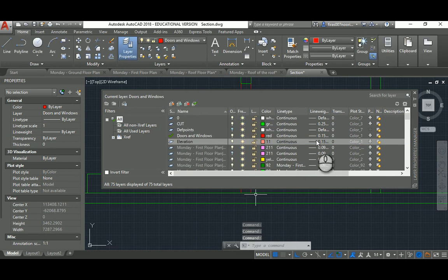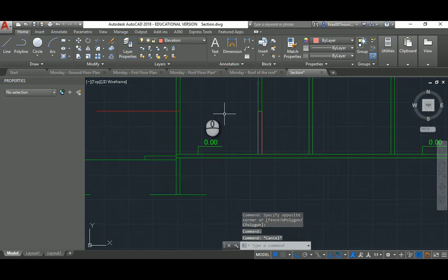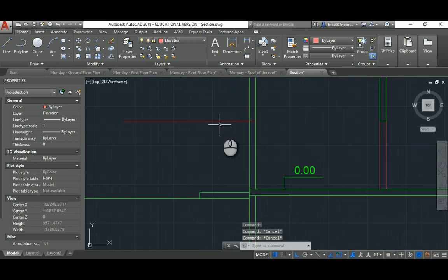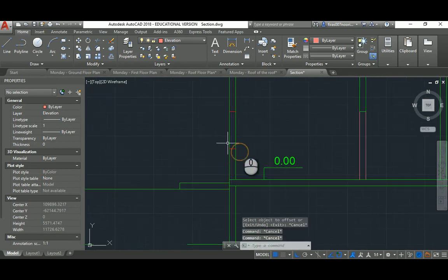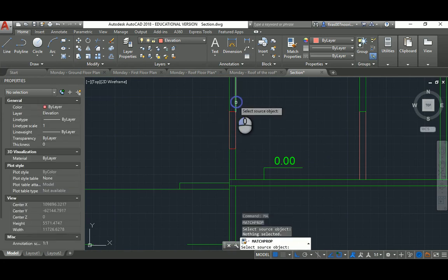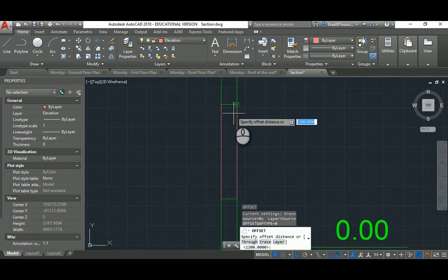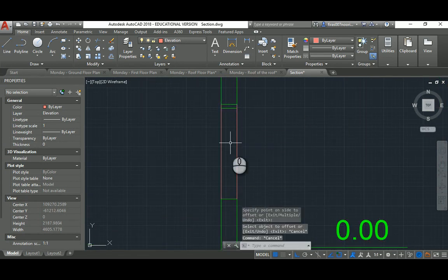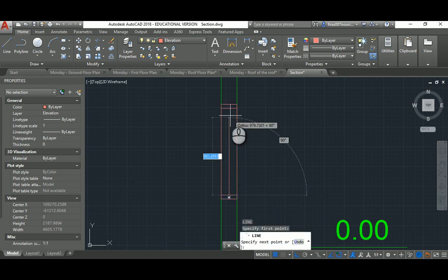And again, it's 15, I'll make it current. So just select those guys, it's just the arc, and just an arch, and then there's just an opening. Here, it's just the window again. I'm going to make it 1200, and offset this 50, rectangle. I'm going to move that down and then align, selecting all those and placing them in layer 0.